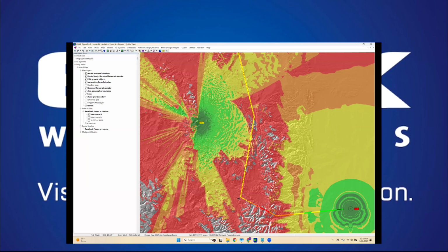Using this route study, you can figure out, will this flight path work, or will I go into an area of no coverage, which, depending on the drone system in question, some of them will fly to their next waypoint no matter what. Some of them will try to fly back to the last place they had connectivity.